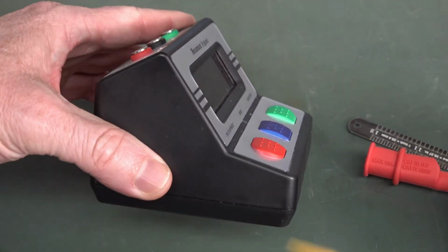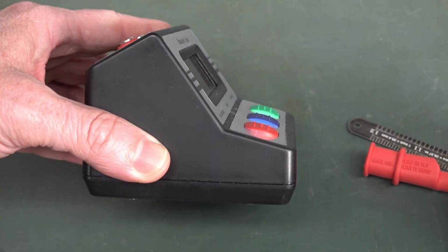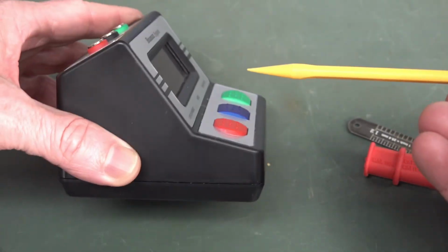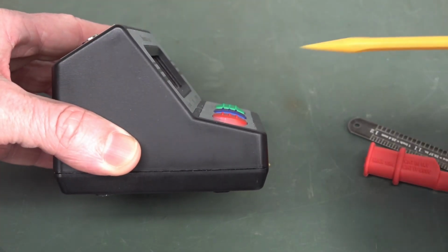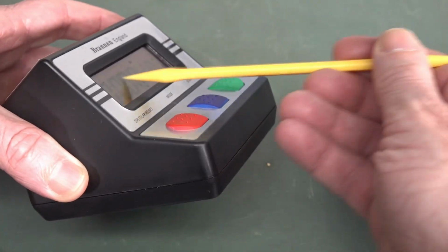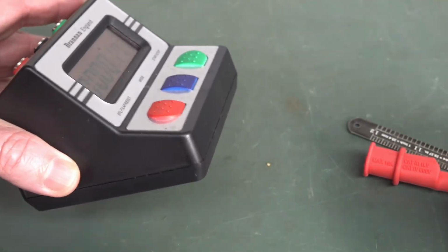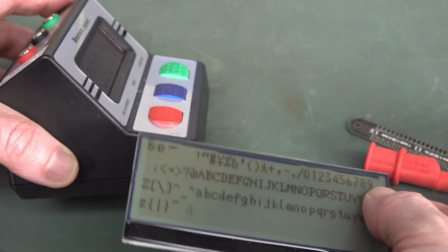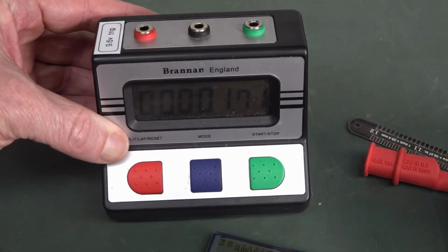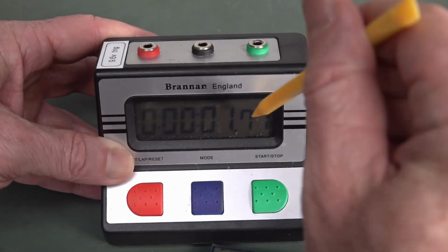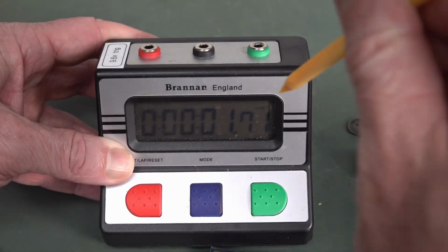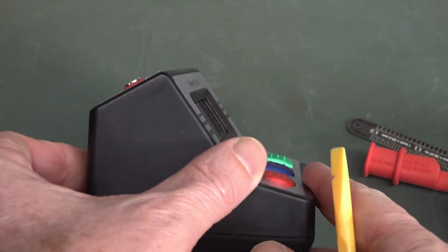If you've got a product like this, viewing it from a long way across the lab, sitting on a bench, you'd be looking up at the LCD. So you want this 6 o'clock one that we've got here. But if you had something that was flat like this and you're looking down on it, then you would want the 12 o'clock bias angle.